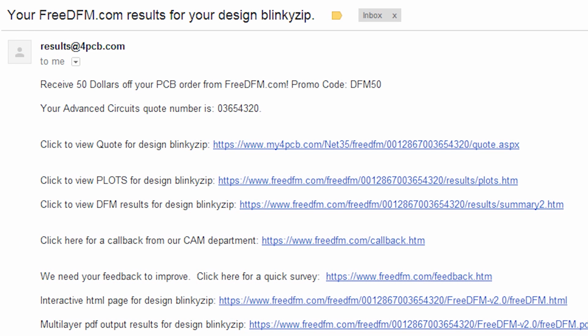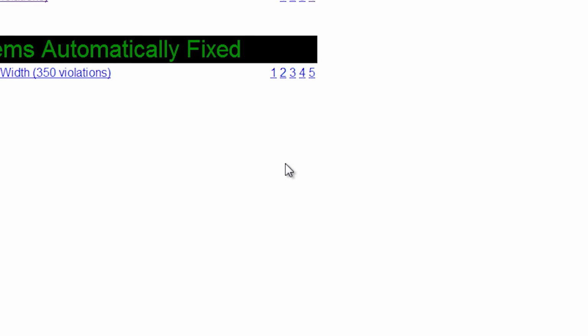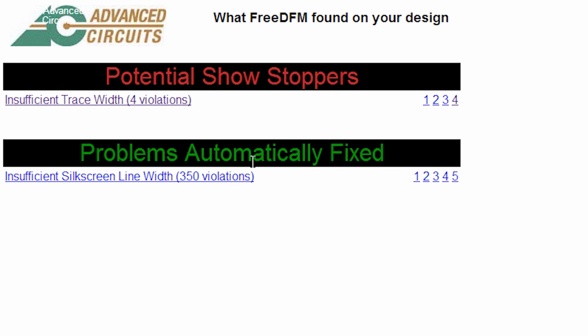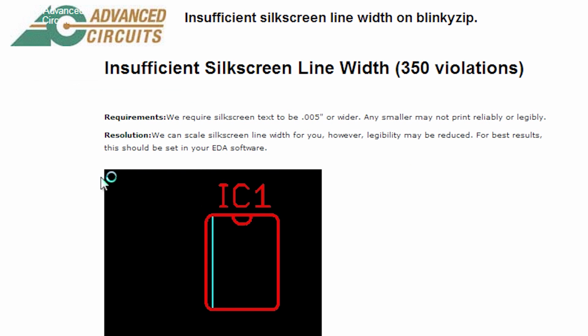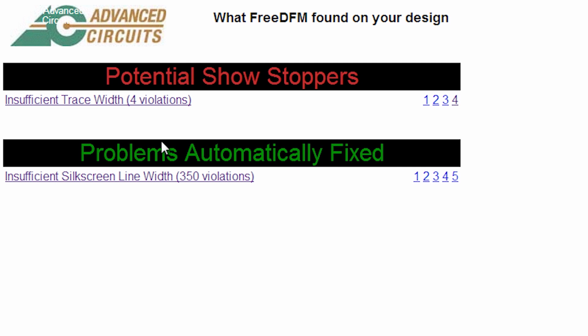By this point, you should have gotten back your design check from free DFM. Again, this is just one of many DFM check services. But you can click here to view the DFM results for the files we uploaded. And now we can see that there's some showstoppers and things that were automatically fixed. So the things that they automatically fixed are insufficient silk screen line widths. That's really not an issue. It means some places we made the silk screen pretty thin and they want it to be thicker to print it. They'll be able to automatically fix that when they fab the board.